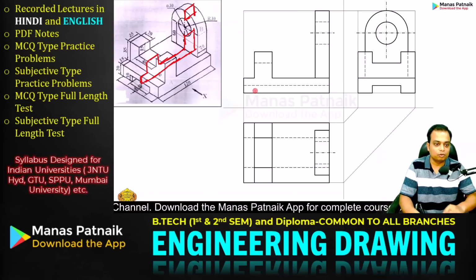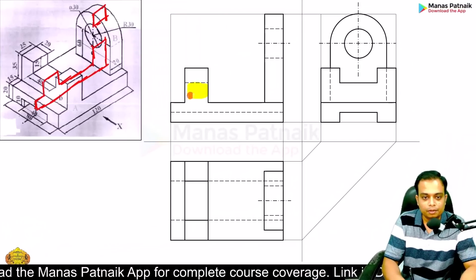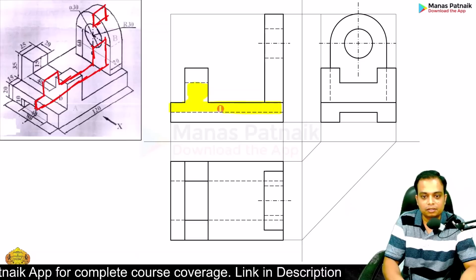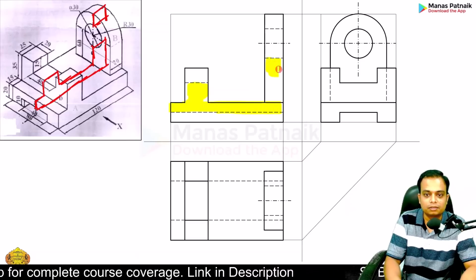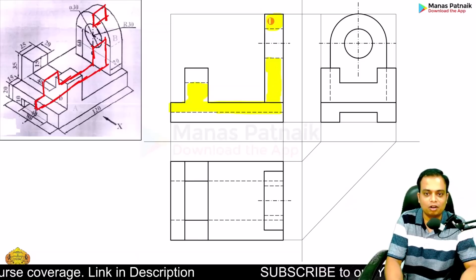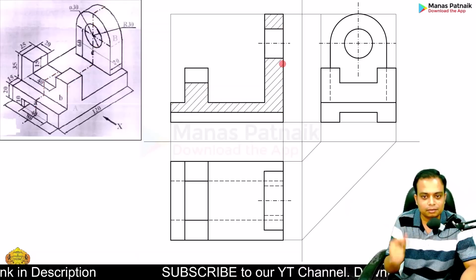So this is how the section would look if I wish to color it. This is the part where you need to do the hatching. Here, this is the hole. Okay, no intersection between the solid and the cutting plane. This is what you need to do, and it would finally look like this.